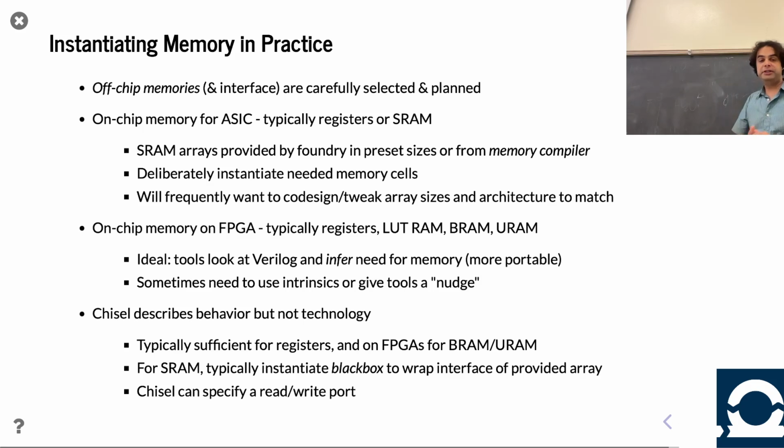On FPGA, you actually have a whole bunch of choices, right? Depending on your vendor, you have registers, sure, great. Sometimes you get something called LUT RAM. You can turn those logic elements into RAMs. You can have BRAM, you have URAM, all sorts of types of memories.